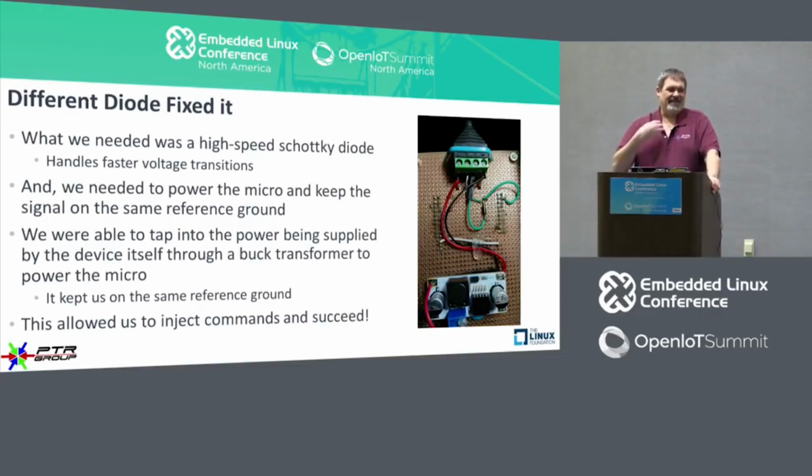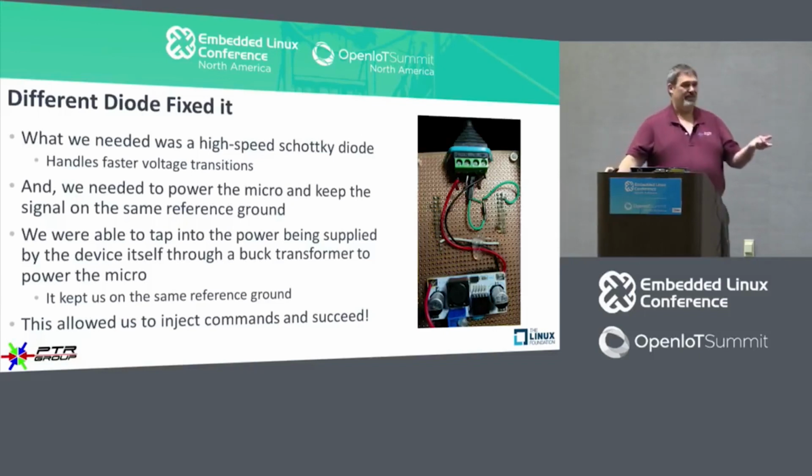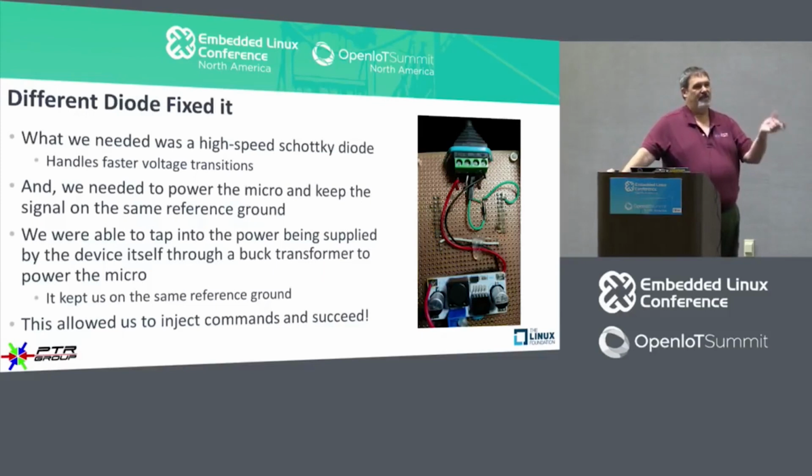So, as a ham radio operator, I go, I bet you they're using AX.25. Let's try that. And sure enough, that's what they were using. When we went back and dug down through the data sheets for the Atmel part, we found that AX.25 was one of the modes it supported. So, cool. This is esoteric detective work, but this is the kind of thing you have to do when you're serious about reverse engineering something.